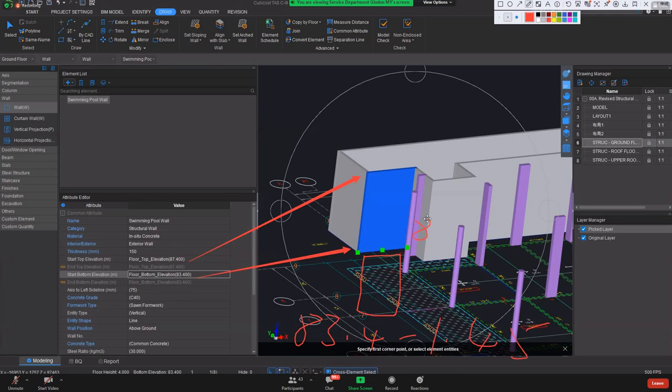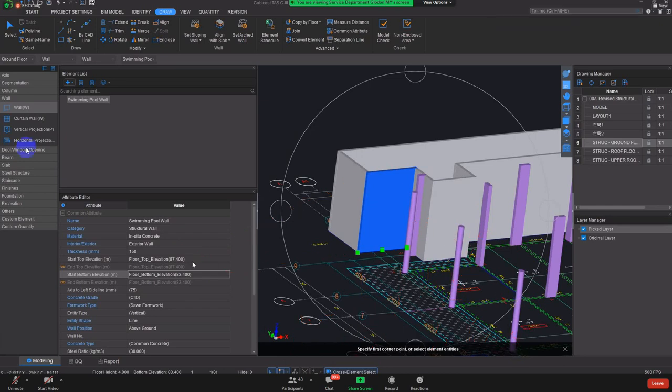And this one you put 83.4, meaning you have the 1.5 height of the wall. Making sense, right? So now, if I put here, either way, floor bottom elevation is 87.4, right? You minus 4, or you should choose floor bottom elevation, enter.